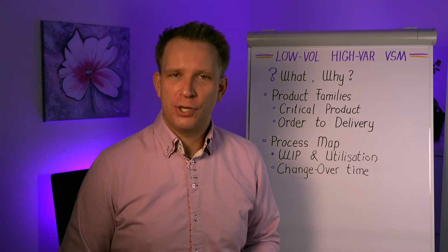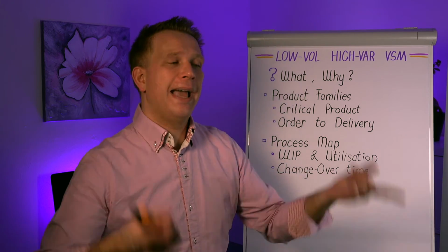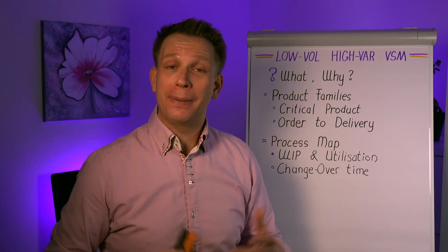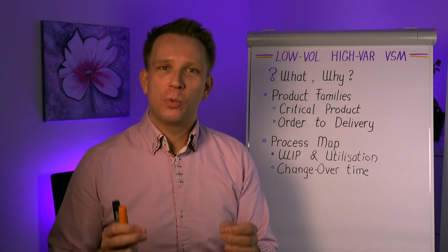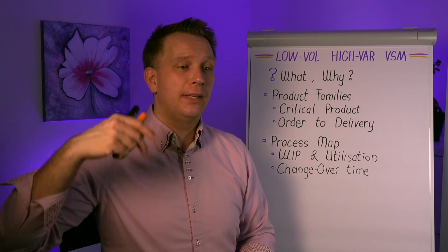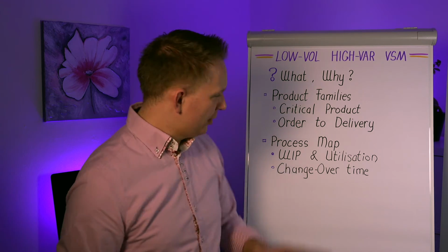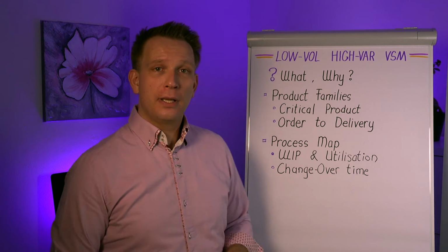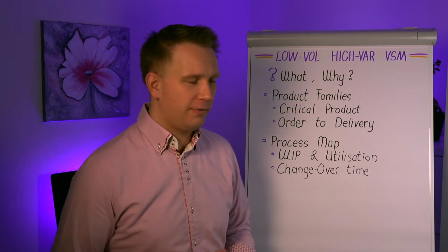If you have a small changeover time, you just do that, get that next one, give it sort of priority, and then do the product that you plan to do as soon as all the parts are in. That can only work if you don't need to prep for hours to make sure that you can run this product.